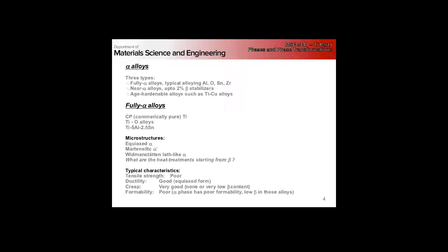Recrystallization. So basically a full anneal, right? We're going to recrystallize and develop a nice equiaxed structure. Does anyone, I guess the people in Mod Sim right now probably have seen this based on one of the exercises. What sort of texture do we get out of rolled and recrystallized HCP?